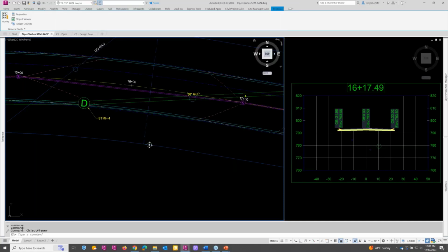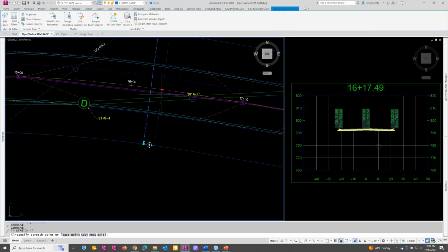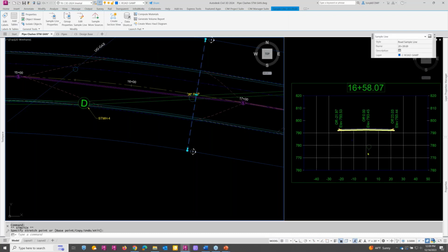So the other way to do it is what? Create a section drawing like we have here and start sliding it along. Take a look at where these things might be hitting. But again, we can see here on the right, we don't really know the difference between these two right here, for example, this sanitary and this storm right here. We certainly probably want some more clearance there, but we really don't know what we have right now.